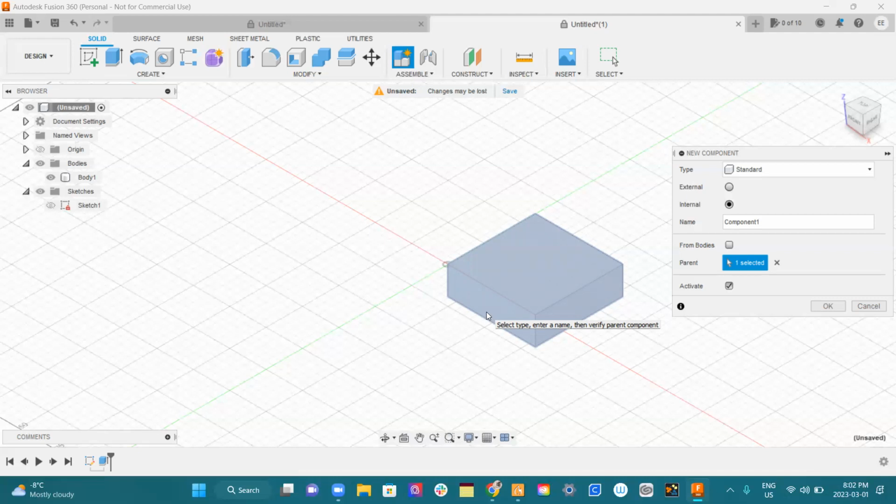Sometimes it does really weird stuff. I've seen it trying to draw out around the thing or draw in under it and do impossible stuff. It's because it gets confused by the way that you specify the setup for it to automatically figure out the drill paths. It's really particular, and it can take a couple of tries. So do yourself a favor and do it as accurately as possible. There's a simulation step that'll come up later.